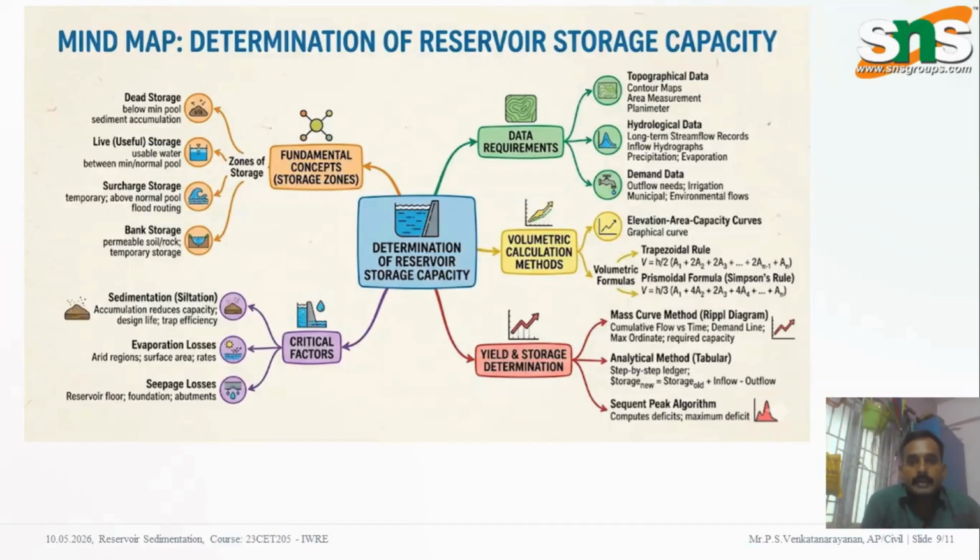This slide presents the key connections involved in reservoir performance. The first branch is inflow estimation using mass curve analysis. Second is capacity loss estimation through sedimentation and Brune's curve. The third branch focuses on operational levels such as full reservoir level and MDDL. Finally, the fourth branch deals with reservoir lifecycle management through testing and hydrographic surveys. This conceptual mind map framework helps engineers understand how different factors are interconnected in reservoir planning and operation. Modern AI and analytical tools can further improve prediction accuracy and decision-making efficiency.